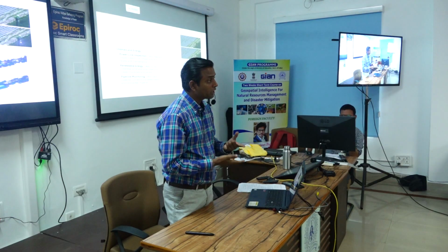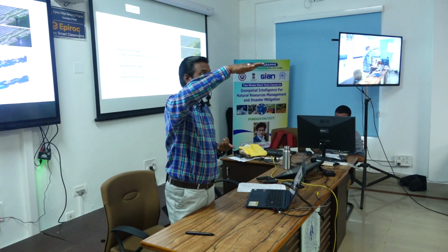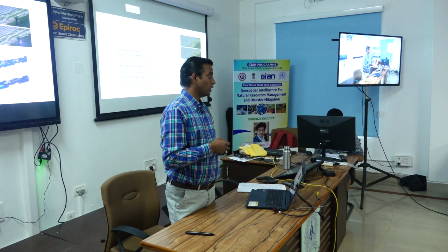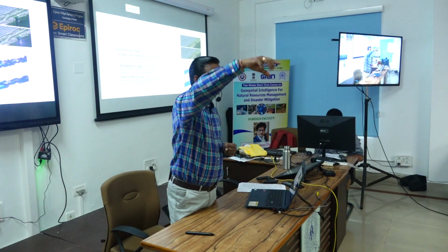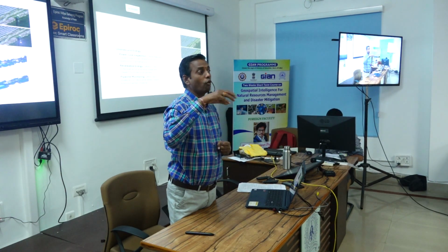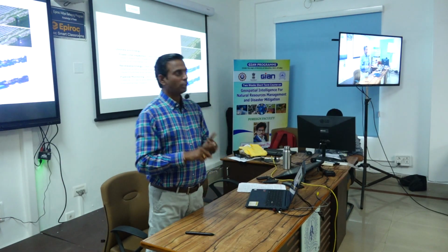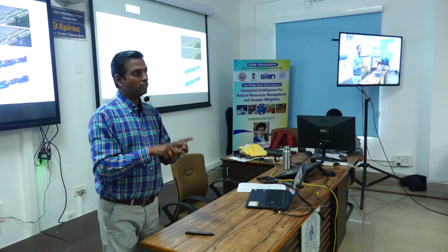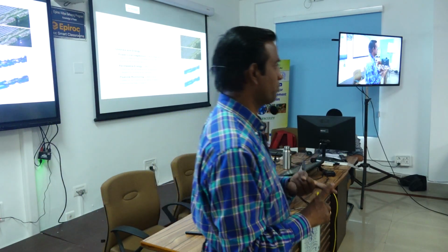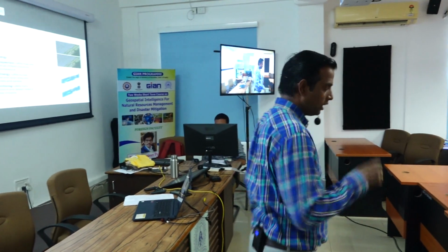But you can use the same drone for surveying. You have to maintain the proper altitude and a proper speed. Okay? In a certain flight path, this many images are to be captured. You have to keep the overlapping area and side lap area and all those things. Now, when using the drone, you have to keep in mind for what purpose you are using it: for surveying purposes or for surveillance purposes. Clear? Okay? Understand, any doubts?